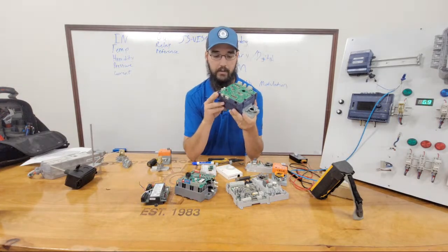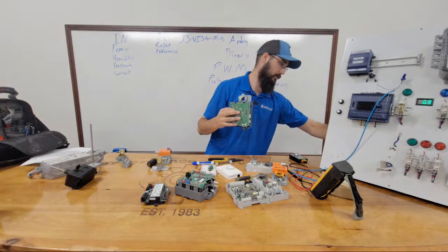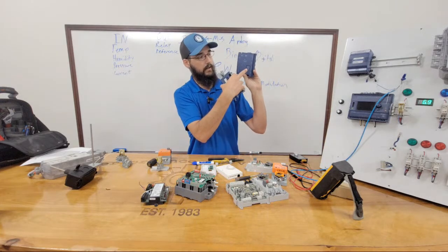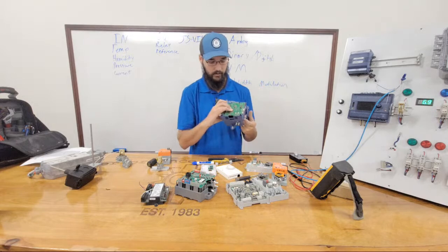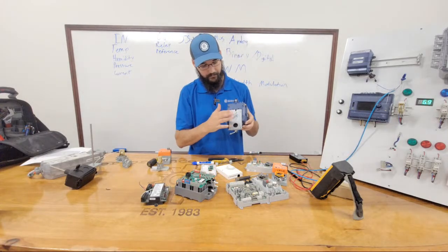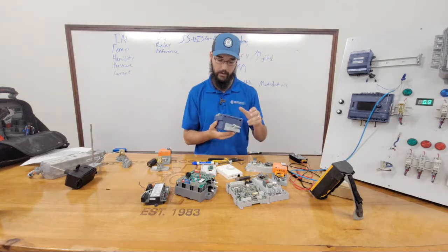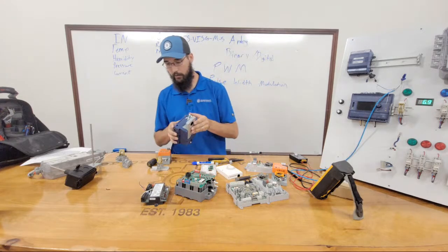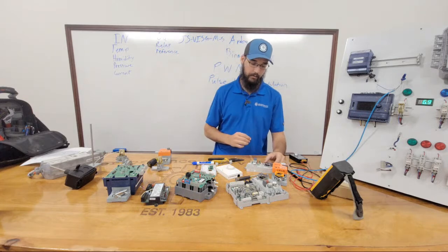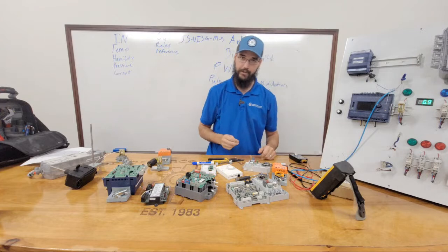On your Distech, there is a clutch, and it's actually on the front panel here. You've got that little button, sticks down, goes down into here, and it is actuating your actuator there. So it's literally a controller mounted to an actuator. All of these are going to be floating point style. One of the most common issues I run into with floating point actuators is their lack of calibration.